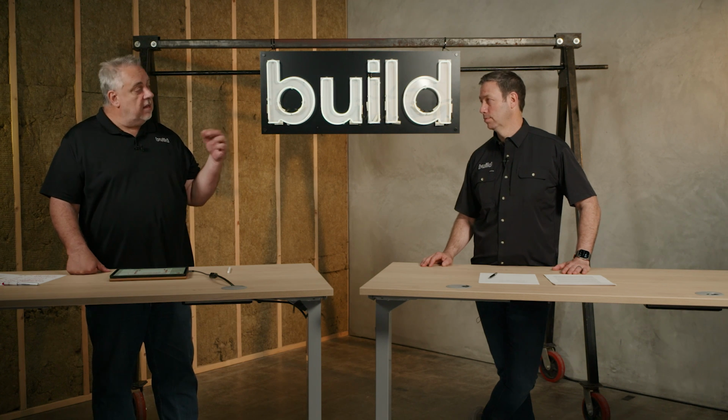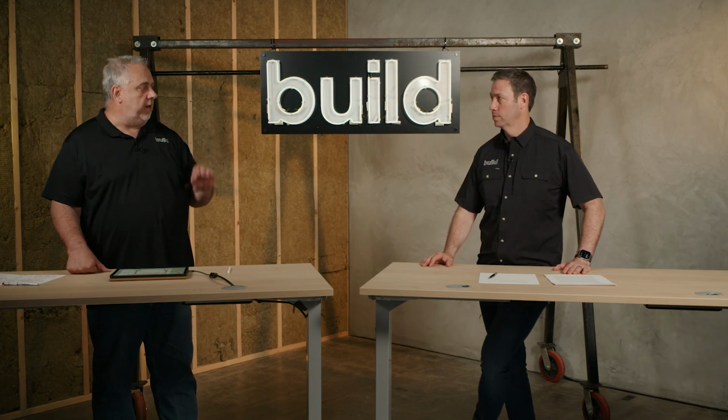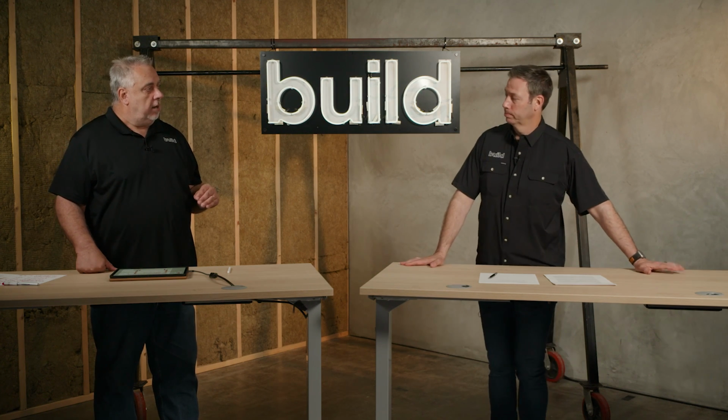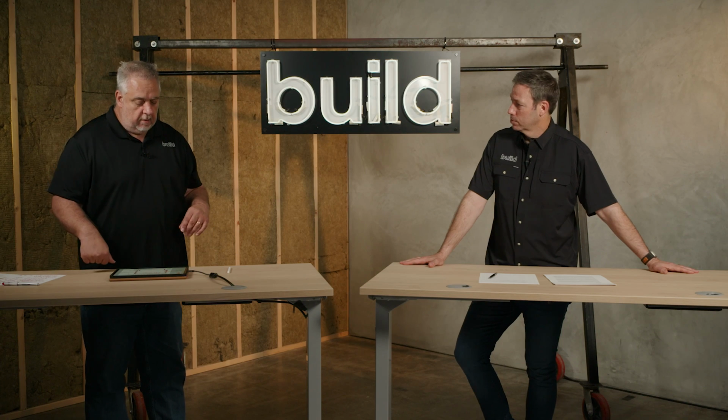I do multiple blower door tests because I like to see what components of the building are contributing to my air tightness. So we did a house years ago. Zip was one of the first products, the first time it was on the market. And so we built the box. I used it as my primary air barrier. We didn't get the windows delivered. They were delayed. So I coaxed the builder into, let's just build a big green box.